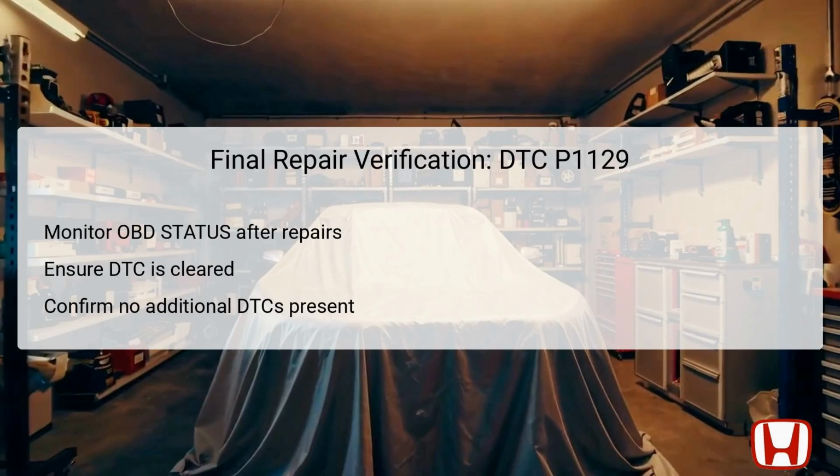Additionally, ensure there are no other pending or confirmed DTCs that could indicate leftover issues. This verification process not only reassures the technician of a successful repair, but also provides the driver with confidence that their vehicle is operating correctly. If the DTC has been cleared without reappearing during subsequent tests, the repairs can be deemed successful.